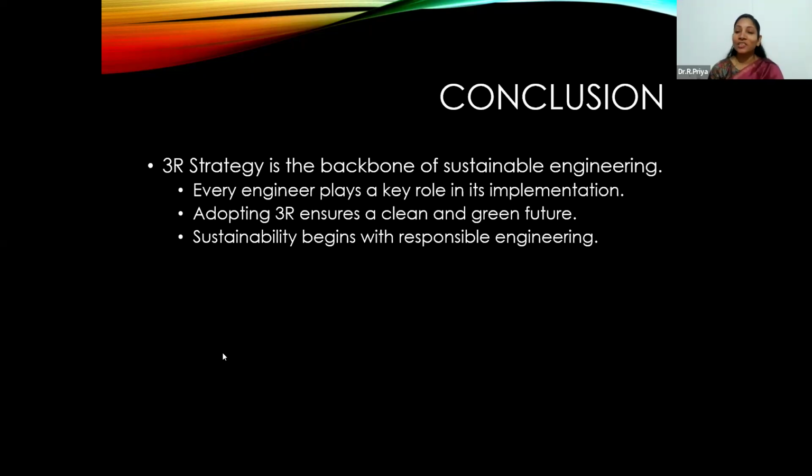Actually, Charles, I just want to ensure one thing. If you go for recycling, the purpose is most important, right? For example, fresh water we can use for drinking, bathing, everything. With recycled water we don't expect such quality, and we use it only for toilet flushing, right? So what purpose we are going to use it for is the most important thing.